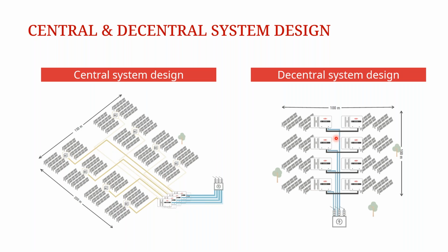The flip side is true for the decentral design, and when you go to the solar Tauro configurator, you will have the option to choose a Tauro inverter that has the capacity of AC daisy chaining. That means you can combine blocks of up to 200 kilowatt on the AC side of the Tauro power and have them connected by the same AC bus, going to the feeding point. When it comes to the central design, you have a lot more flexibility as far as other choices, even having integrated AC disconnectors inside the inverter.